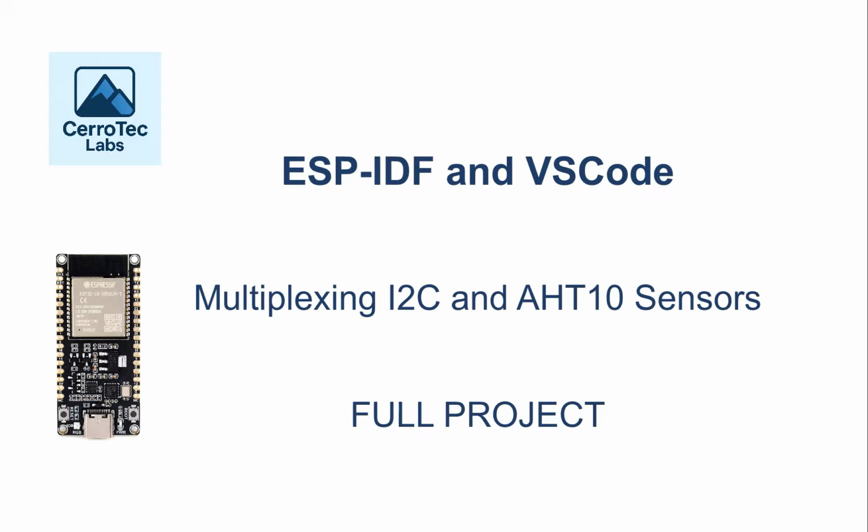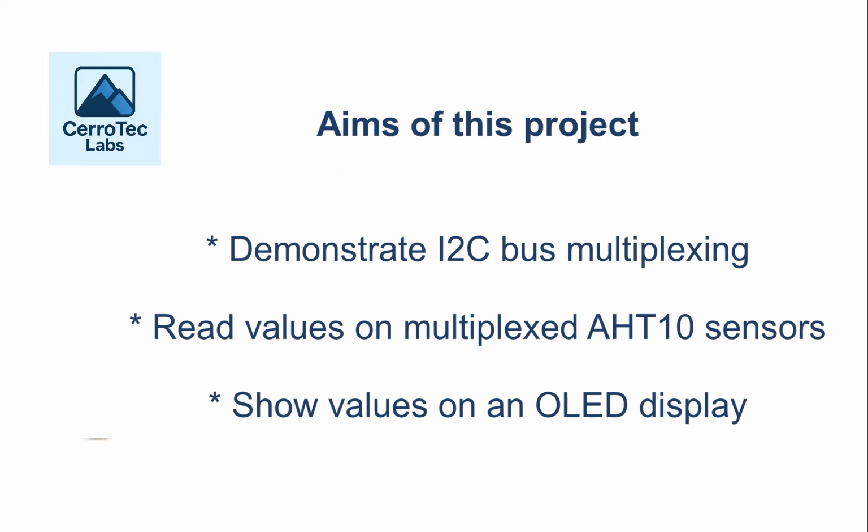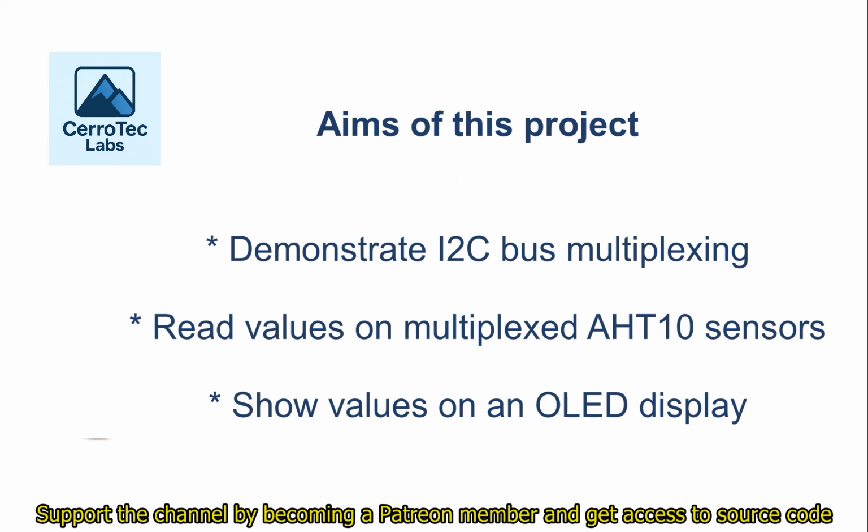In this video we will develop the code to multiplex sensors on the I2C bus. Let's take a look at what we'll be covering. The aims of this project are to demonstrate how to multiplex sensors on the I2C bus, to read the temperature and humidity values on the multiplexed AHT sensors, and to show the measured values on an OLED display.